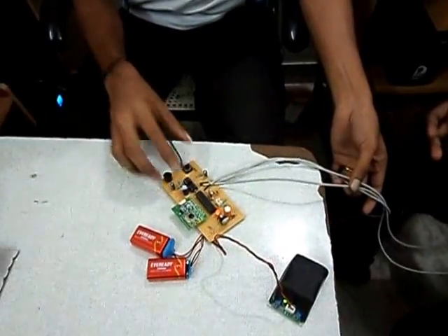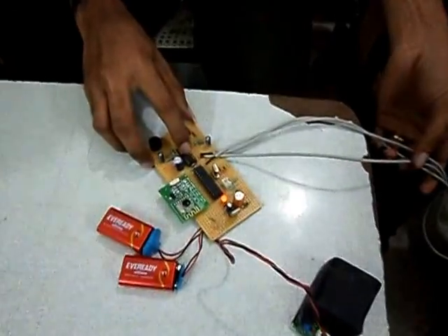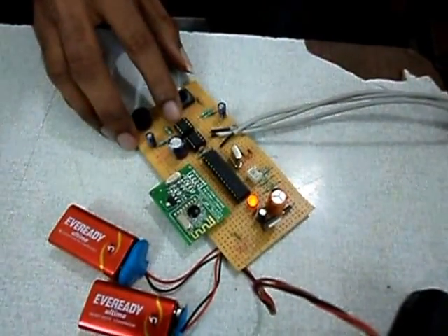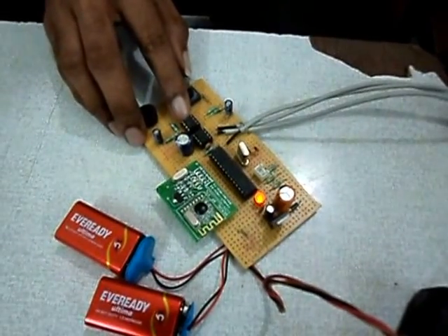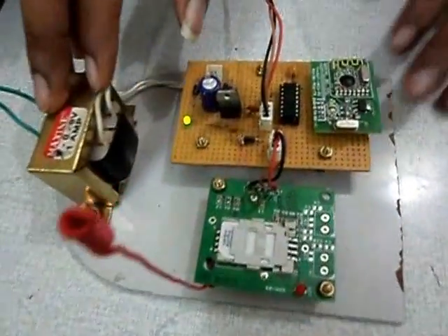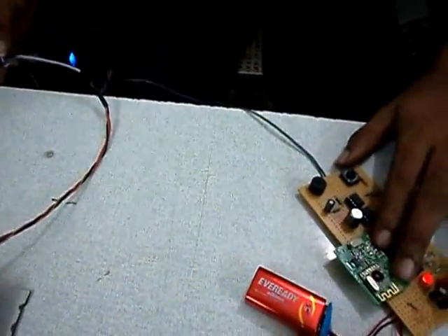Since the ECG signal is in the millivolt range, we have an instrumentation amplifier AD620. The amplifier boosts the signals, and we have used a UA741 IC to improve the gain factor. We are connecting to the system using the audio jack input to LabVIEW, and this is a remote module through which we are going to get the data from the Zigbee used by a patient.